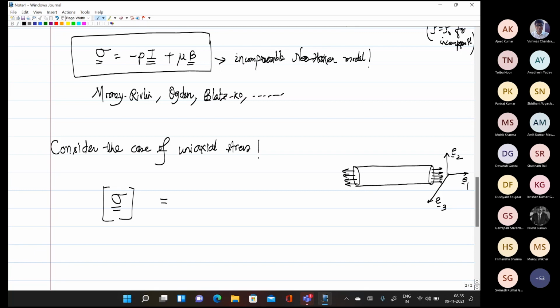In reality, you have to clamp the ends of the beam, and wherever you have clamped it, that part does not undergo any deformation. And that's a slightly complicated example, if you really look at it deeply. It's not the case of uniform deformation, the actual test that you do, because close to the points where the beam is clamped and away from those points, the deformations are not similar. Have you noticed this?